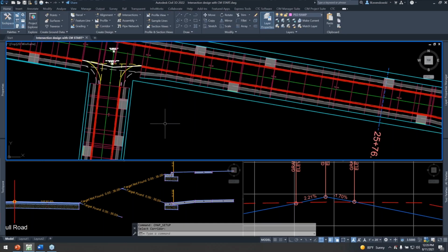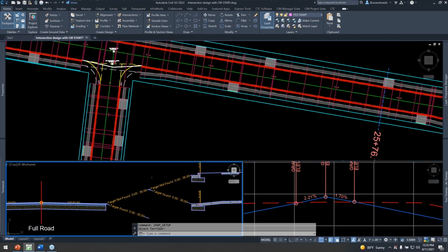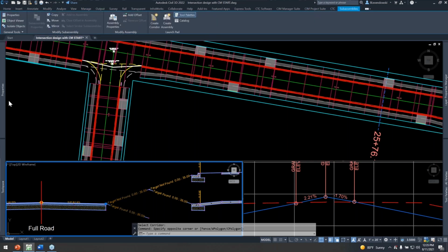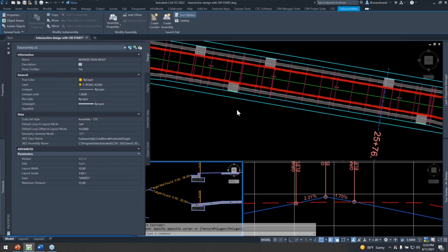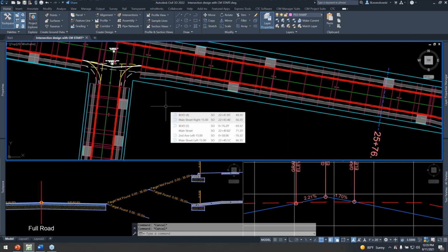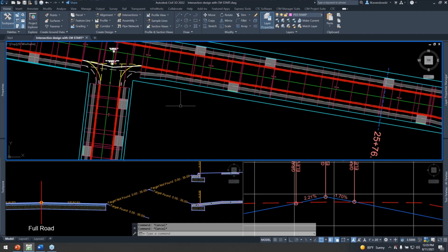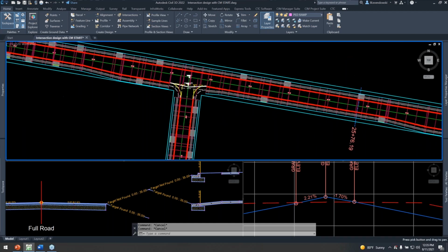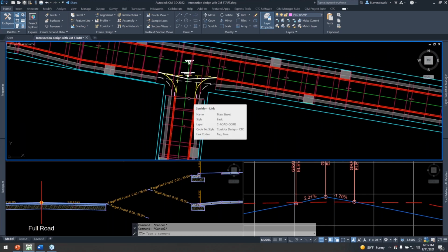You guys have seen me referencing things by styles and layers, okay? The naming in corridors is still just as important. What do we name these subassemblies? That's important, right? What do we name the layers and the styles I'm assigning to objects? If we're going to leverage layers and styles and all this stuff to be linking to our subassemblies, it becomes important to keep track of that. I'd kind of stumbled into something there, and it becomes very easy to back out of it because that naming is important. And that's not something I can write a tool for to fix. That's just something you guys have to get used to.